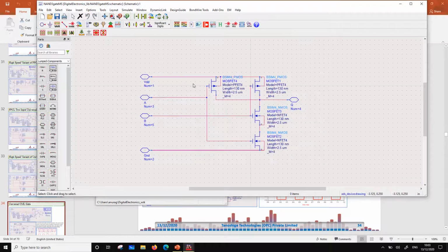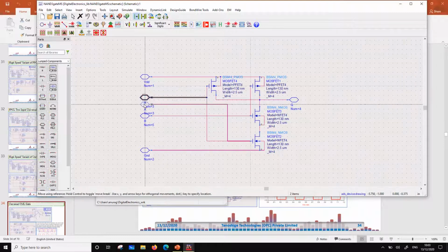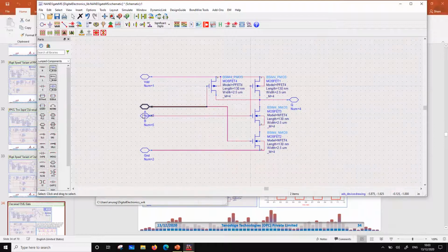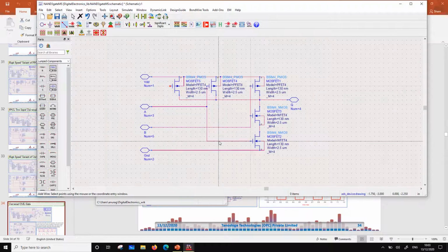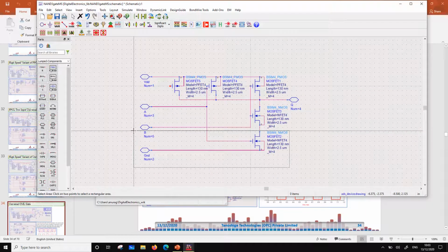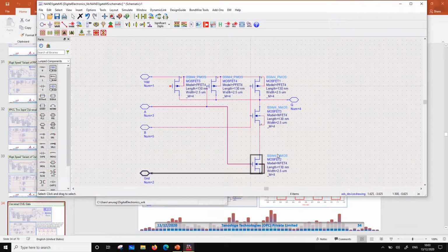Okay, so what I'm going to do is take this block and repeat it. Before that, let me pull this down a little. Okay, so I'm going to repeat this block as another transistor over here, and I'm going to connect this like this. Done. And then the same thing I'm going to do with the pull down circuit. I'm going to introduce another block here, another transistor actually.